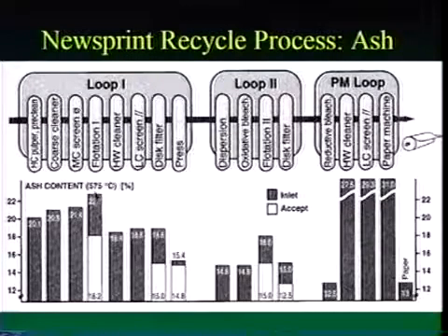And then as we go to flotation, the flotation drops our ash from 23% down to 18%. Why? Because flotation can remove some of that ash as a sludge that goes with the ink. Then we have our ash at 18%, and then we wash out some of our ash with our disc filter. So our washing process can remove some of our small ash, and so now we're down to here. All right, now our ash levels are lower.